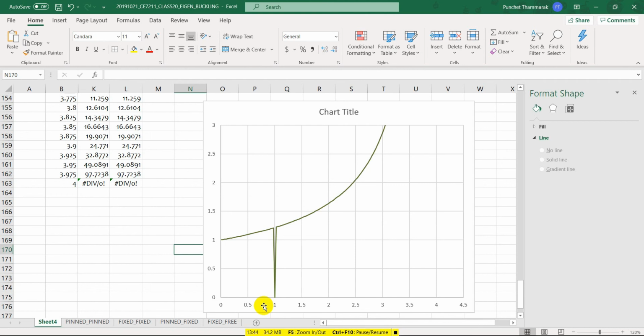Now, under the presence of compression, we're going to use the PO/PE ratio like before in the former homeworks. So I gave you like 4, 5 PO/PE ratios. I don't remember that. You just use those numbers. So under compression, at the midspan, you will not get just 1.0.